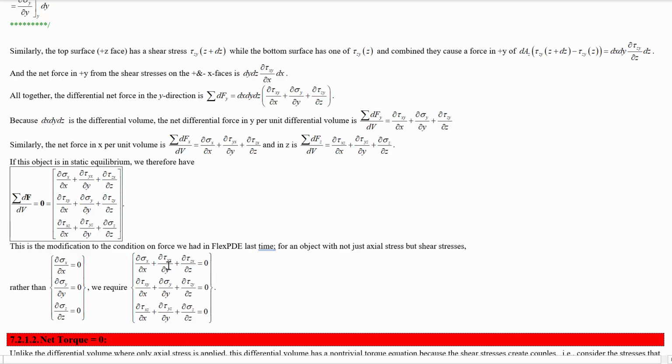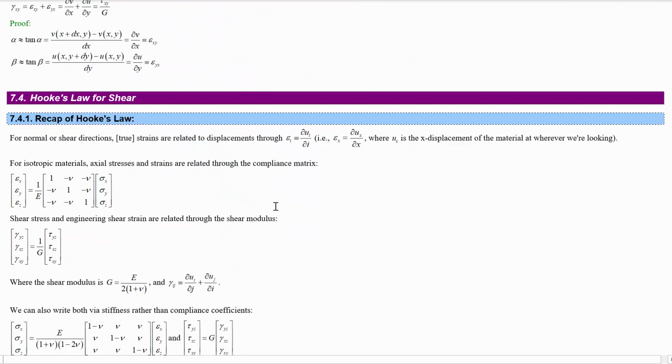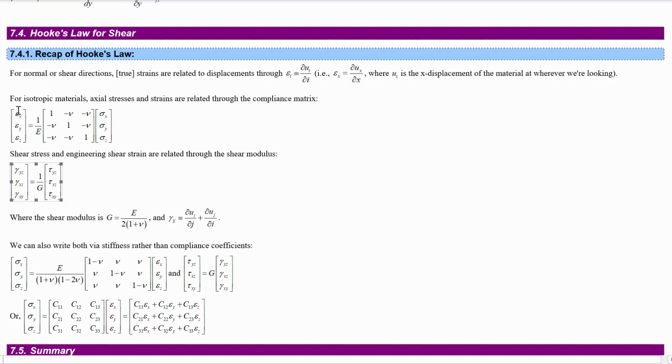So it's not actually 9 unknowns in this. It's just 6 unknowns. Then we have extra equations coming in to help us out from the elastic definitions and the relations between the stresses and the displacements, once we also combine this stuff, the Hooke's law, with the derivatives of displacement in each direction.